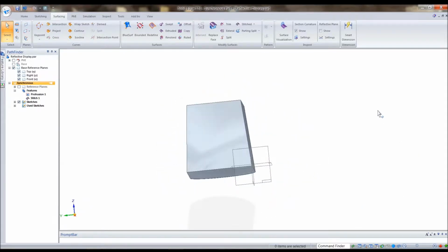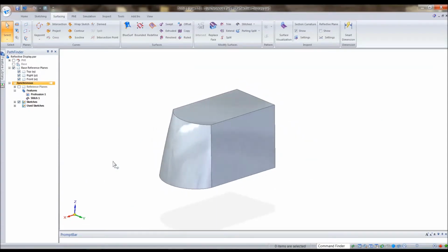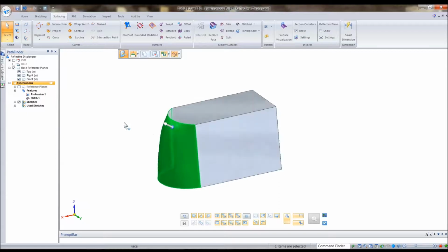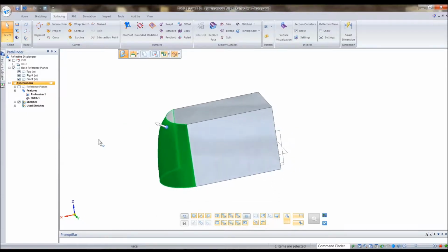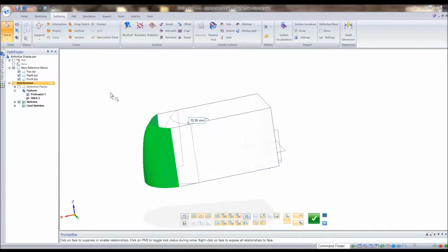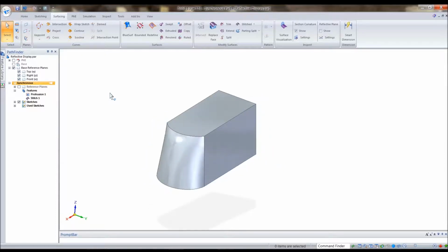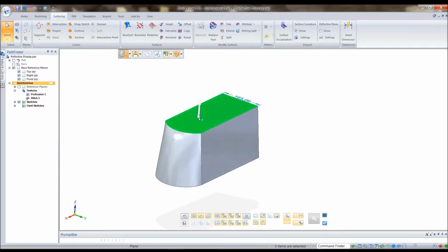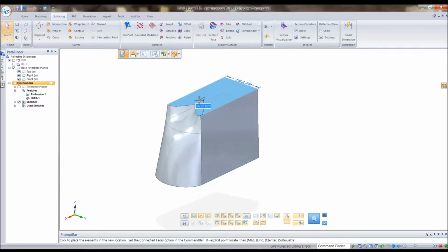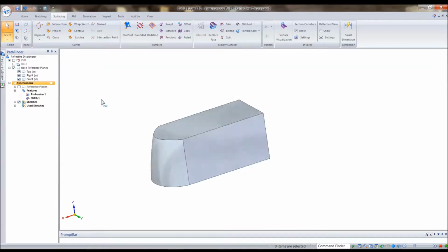One of the limitations in synchronous now, though, is that I can't go back and change those surfaces and make a change to the part. I've got to physically go in and grab these things and move them. So I don't know if I can even move this guy. Let's see if I can move this out. Yeah, there we go. So now your body is basically the king, right? Now the body is what's really doing all the work. And see, there's some issues going on in there, and so again, this is synchronous, and that's a whole different modeling.